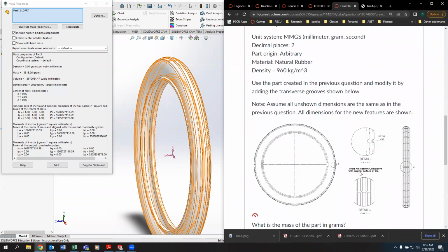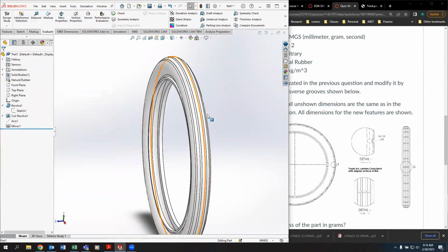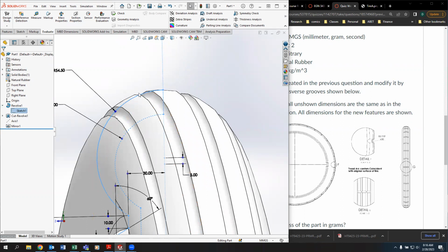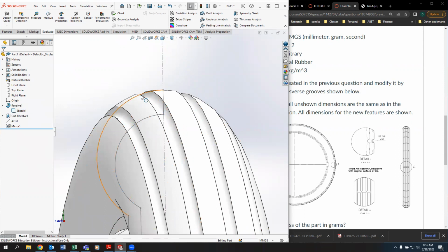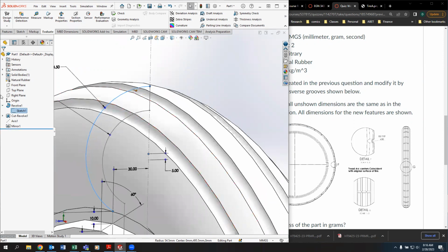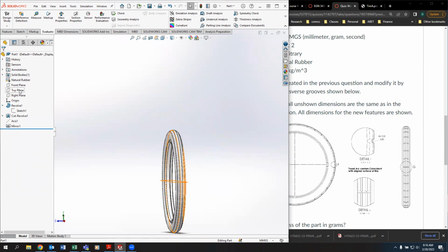This slash section here is a little bit tricky because it wants us to make a groove in the tread on the perimeter of the wheel, but in the transverse direction. This is tricky because it requires us to remember what the diameter of this arc was, or at least know to look for the diameter of this arc. And again, if I want to, I can even show this sketch again, so that I have this arc that I can manipulate as part of my features. Although we don't have to do that, and most of the time, if we can, we prefer to use things that are a little bit easier to work with.